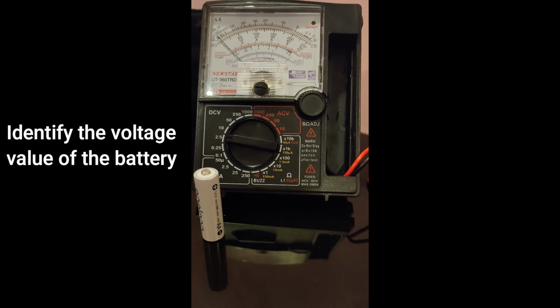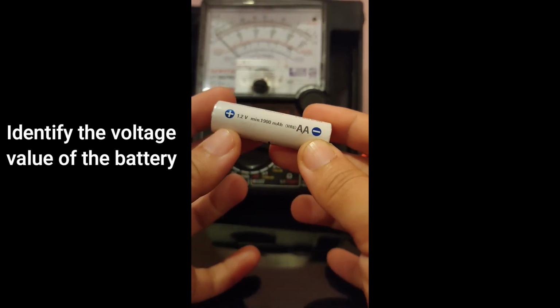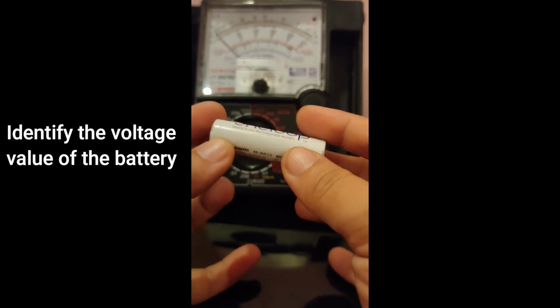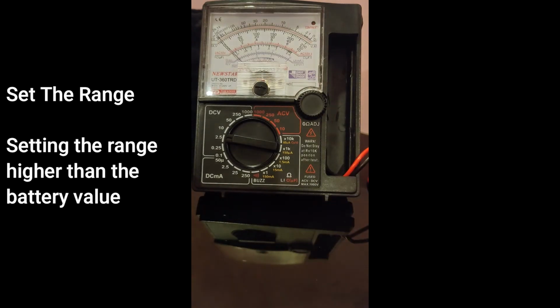First, identify the value of the battery. This battery has 1.2 volts. It is a rechargeable battery. After identifying the battery, you are going to set the range of your multimeter.